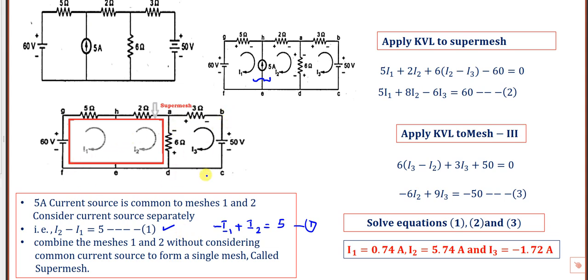So we got one equation from this; two more equations are required. I can apply KVL for the super mesh. While applying KVL for the super mesh, a very important concept is that you have to consider the original currents flowing in the elements. In the 5 ohms, if you're taking a drop, you have to consider I1. While taking a drop across 2 ohms, you have to consider I2. In this mesh 2, you have to consider I2. For this problem, you cannot apply the inspection method, so you have to write KVL only.